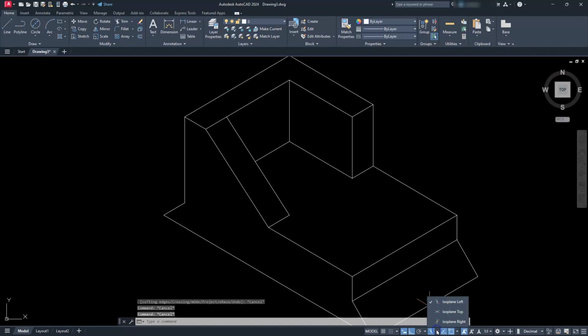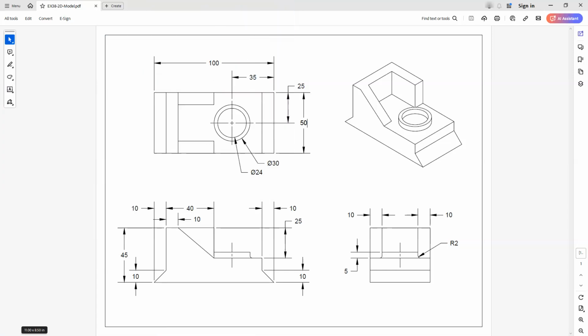So let's go ahead and switch to the isometric top. And then we'll take one more look here at the drawing and see how we can position that just by using a little math. Okay, so on this one, the math is really not too complicated, right? We know that we have a surface, and it's probably easy to draw it on this one, is that at this midpoint here is where the center of this circle is. And the reason I know that is because this number here is half of our 50, right?